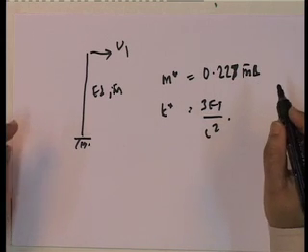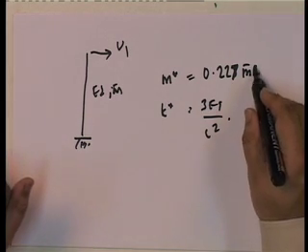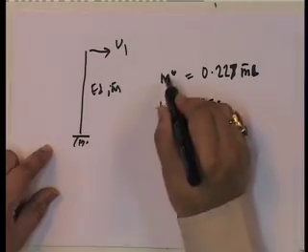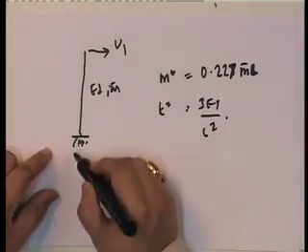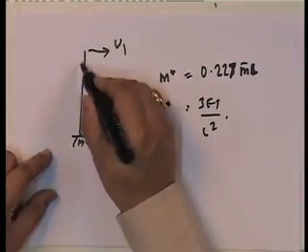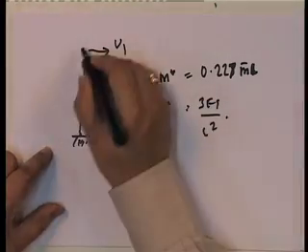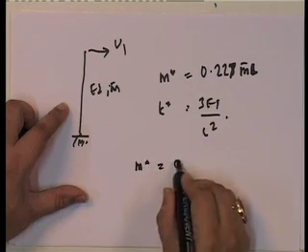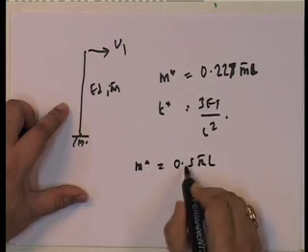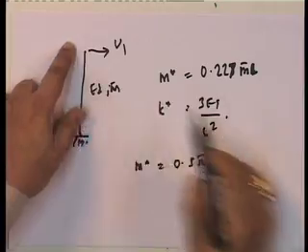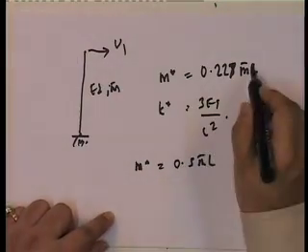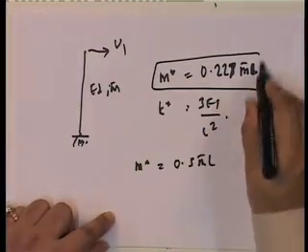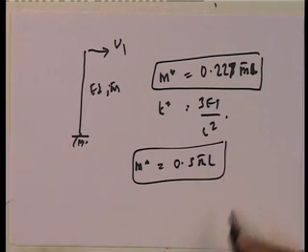Now, if I were to do this, and I say that look, this mass which is over here, I'll lump half here and half here. If I do that, what does my m star become? My m star becomes 0.5 m bar L. Obviously, when I do this, half the mass goes. You see how ridiculous this is? If you use it in this kind of a situation, this becomes completely ridiculous.